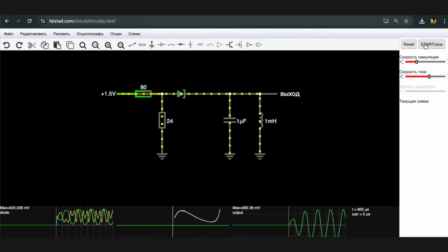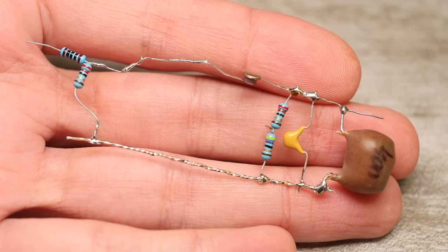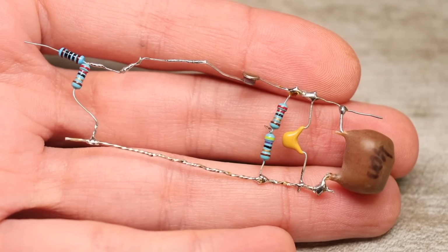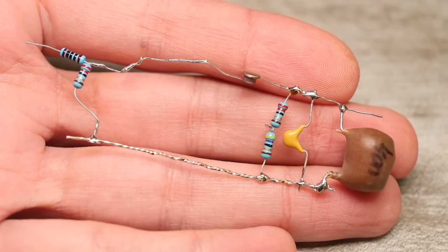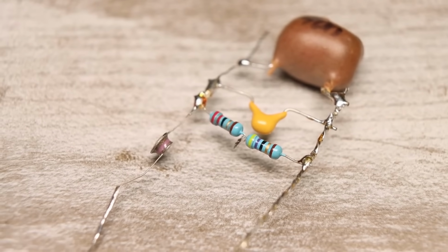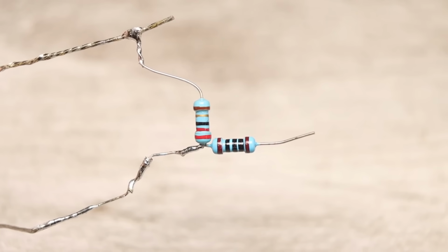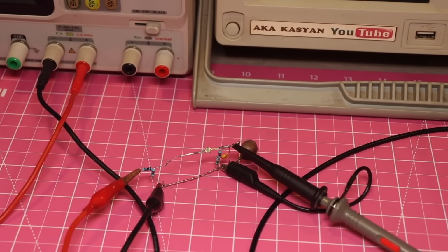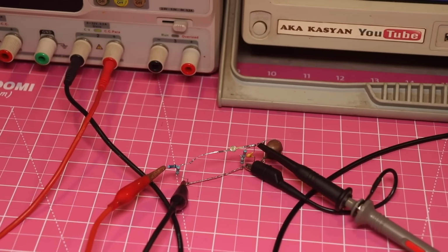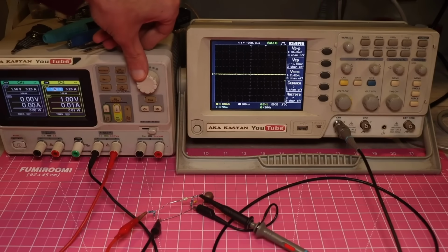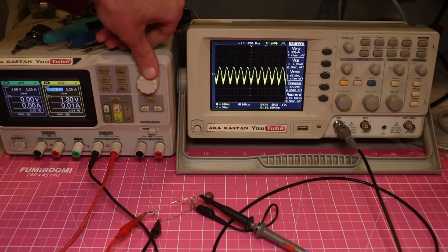In practice, this region allows for the generation of oscillations and, for example, makes it possible to build an LC oscillator using a tunnel diode. In its simplest form, such an oscillator would look like this. It consists of a power source, the tunnel diode itself, an LC circuit, and several resistors. The power supply, in this case 1.5 volts, is applied to a voltage divider. These very resistors set the voltage across the diode and are chosen so that the operating point falls within the region of negative differential conductivity. That's what makes the magic happen.